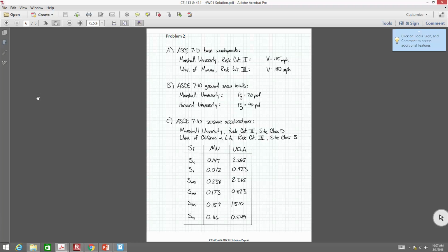How do we get from our modified accelerations to our design accelerations? We just multiply them by 2/3. That comes from code specifying bodies and engineering judgment, basically saying we really only need to use about 2/3 of that acceleration for the purposes of design. Everybody good? Yes, sir.